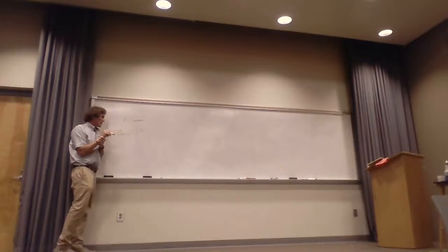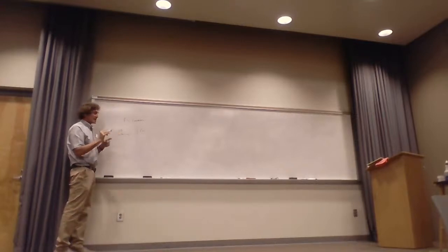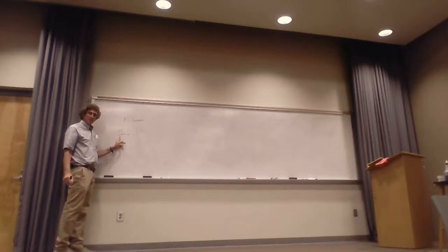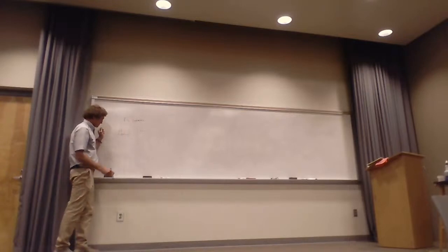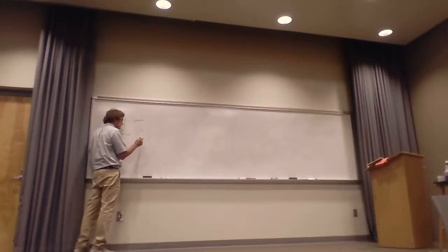All right. Help me out here. Say that again. The E field out here? I'll just read it. It says a 200 megahertz uniform plane wave incident on a thick copper slab imparts a 1 millivolt per meter amplitude at the surface. How much power passes through a square meter at the surface?